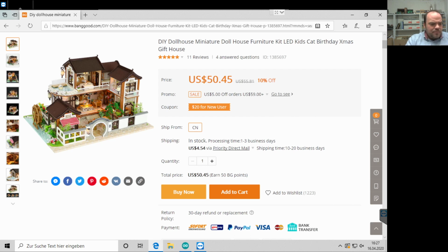They come with a lot of LEDs. I think 10, 9, I forgot now. But with a battery box, so you can only have the lights at the same brightness. And I thought, hey, let's try something. I have some of these TLC 5940. Let me get it here. Hope I can read it. It's a TLC5940, a 16 channel PWM controller for LEDs, so especially for this purpose.